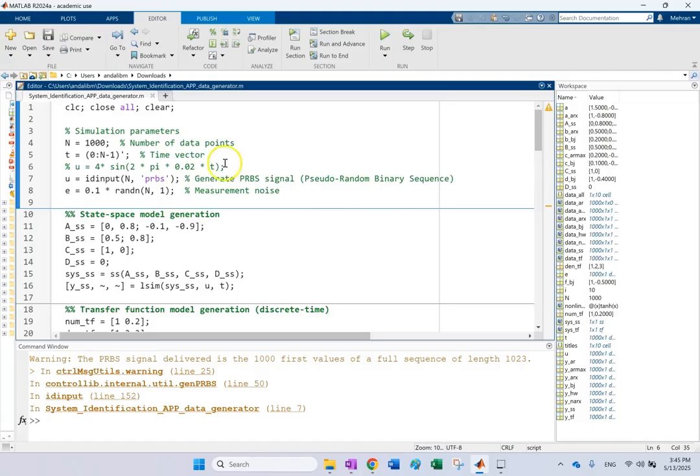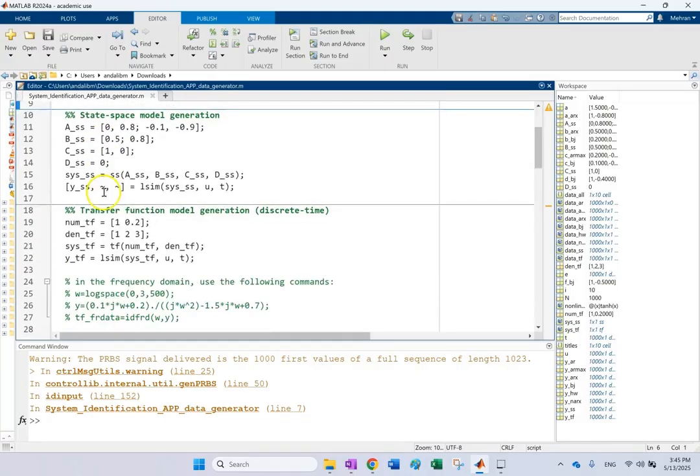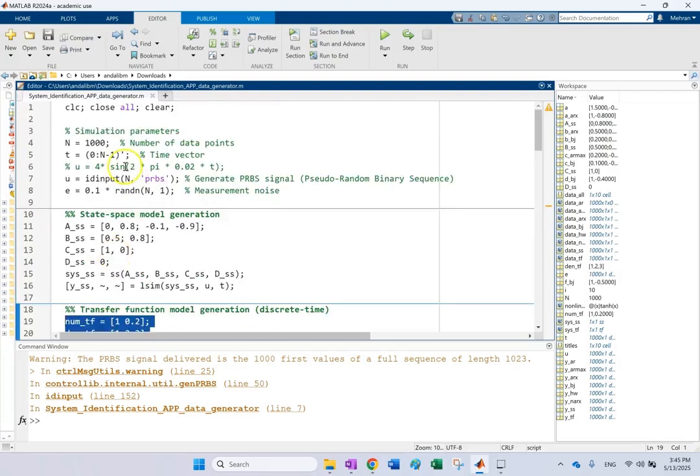Typically in a linear system, a simple guide is, if you have n unknown parameters, make sure you have n harmonics in your input. For instance, if I look at this transfer function, which has 1 zero and 2 poles, at least I need 3 harmonics in my input to be able to find all of them.